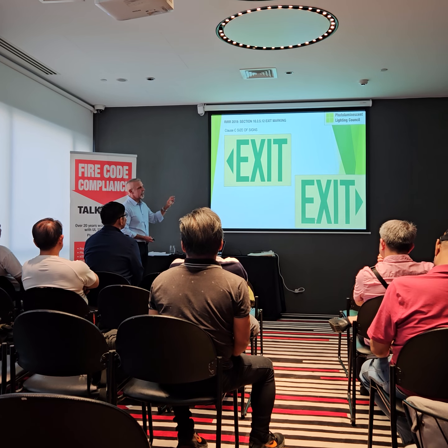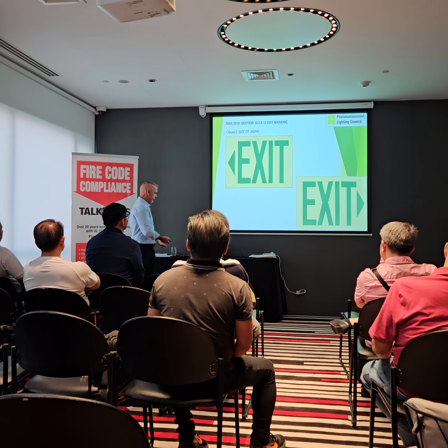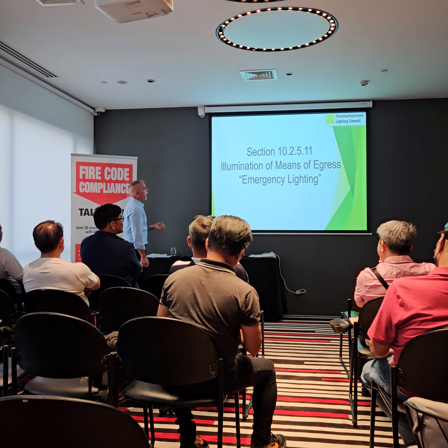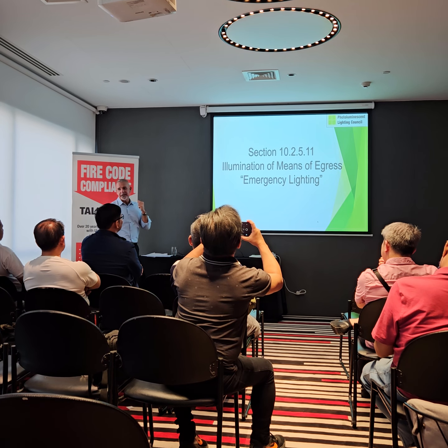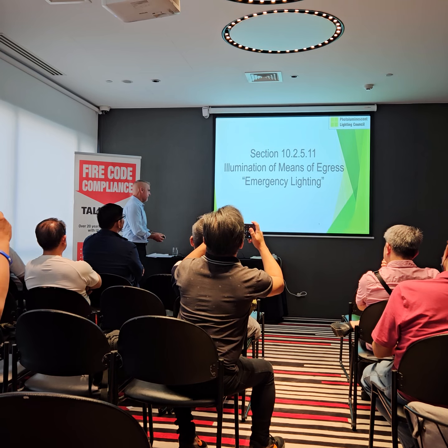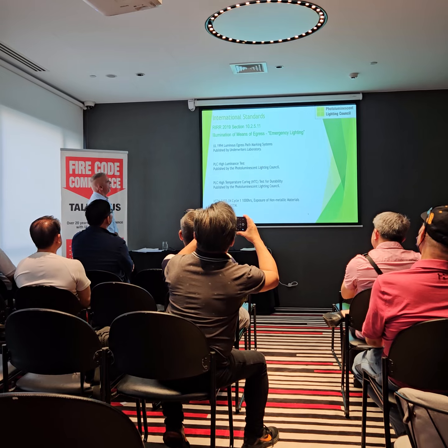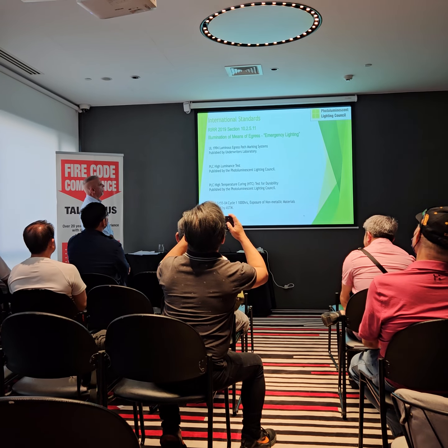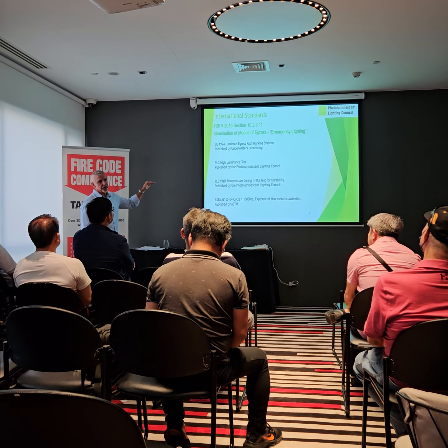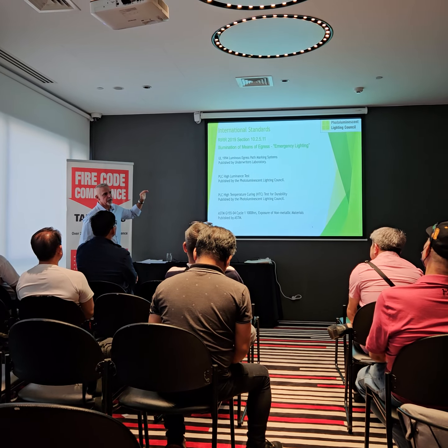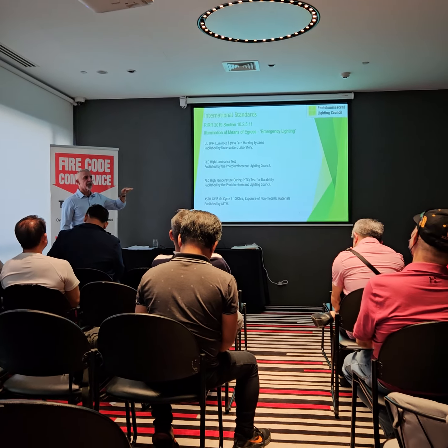There are some unclear things, but again, the size of what they want is pretty clear. Right, so the tricky one, emergency lighting. It specifically says that you can't use photoluminescent products to fully replace an emergency lighting system. So, okay, got that, we understand that.